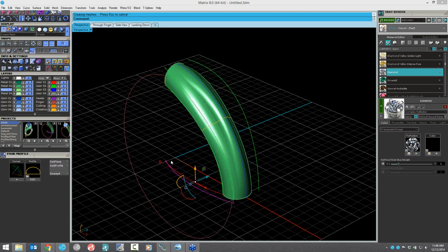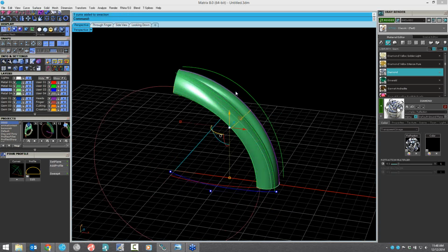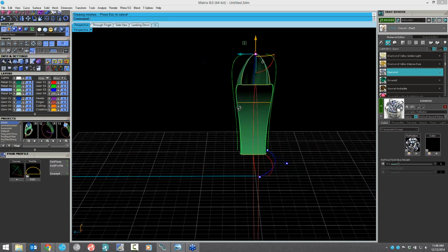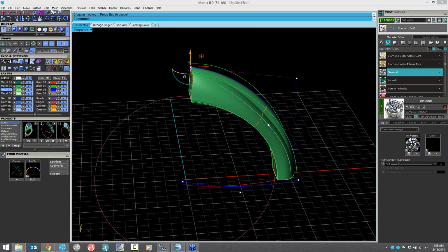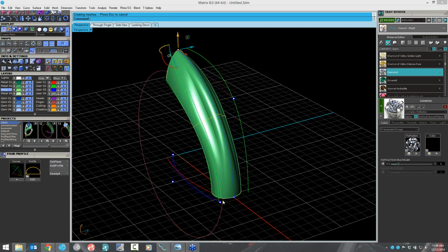And I can come in here and say, all right, well, I want to just move this over and pinch that in. Or I can come over here and select this curve and turn on control points and maybe raise that up, make that taller. So the whole while, it's sitting and putting those profiles through those 4 rails. Okay? So there you go.